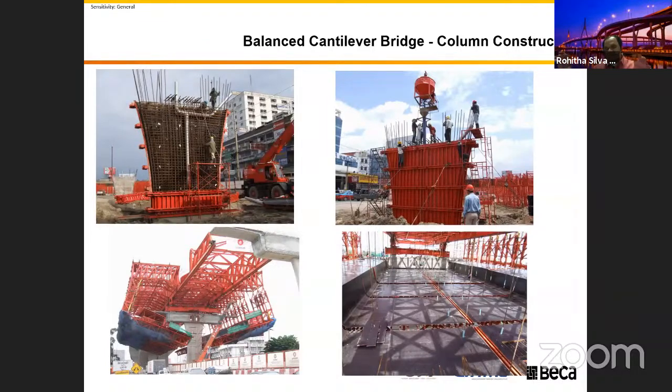When the designers design it, it is a straight bridge, a continuous span bridge, maybe 400 meters in length, for example, expansion joint to expansion joint. But when you are building it, you build your column, of course, no problem, but you build the section of the box girder or the superstructure monolithic with the column, and then you build the rest in between.